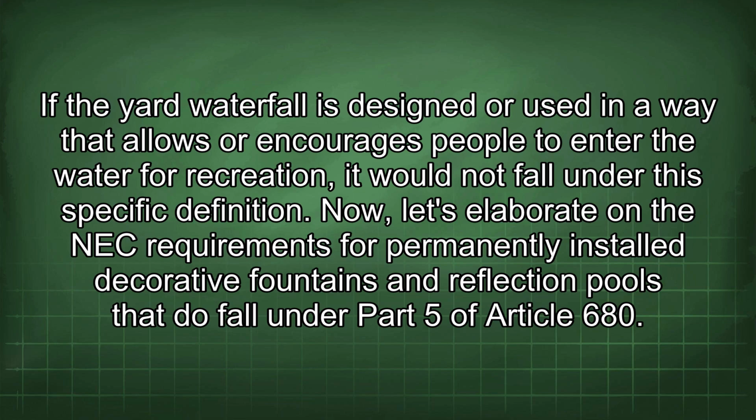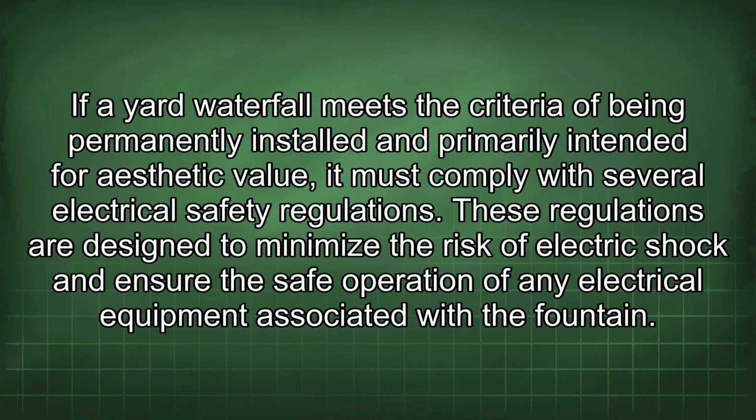Now, let's elaborate on the NEC requirements for permanently installed decorative fountains and reflection pools that do fall under Part 5 of Article 680. If a yard waterfall meets the criteria of being permanently installed and primarily intended for aesthetic value, it must comply with several electrical safety regulations.